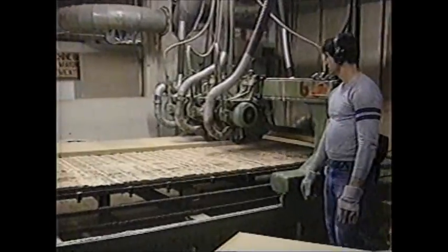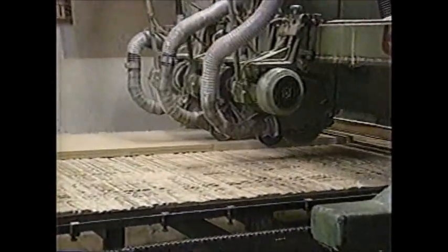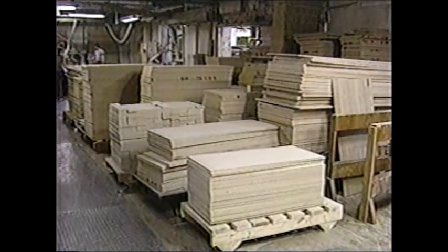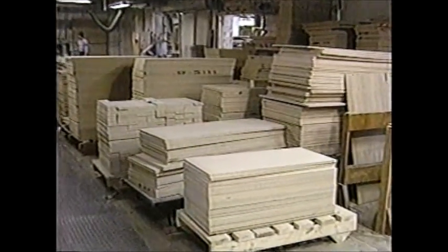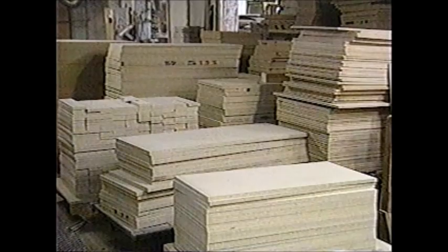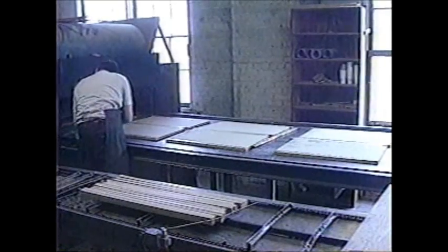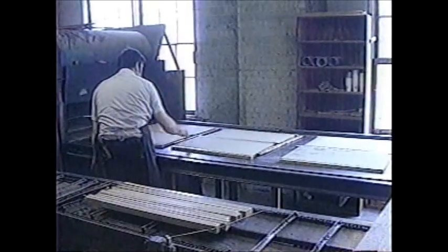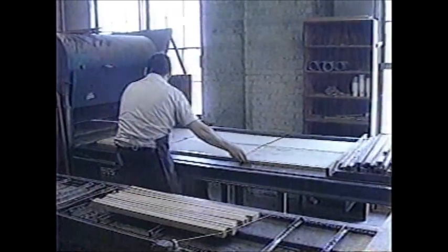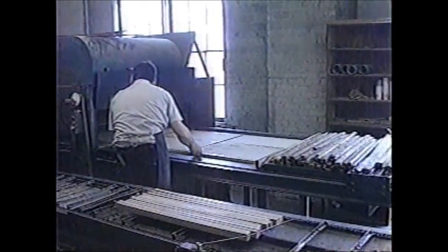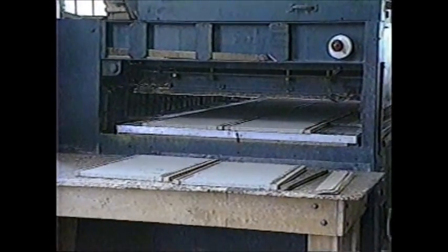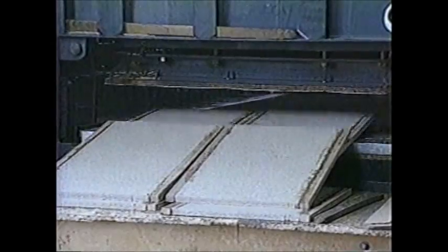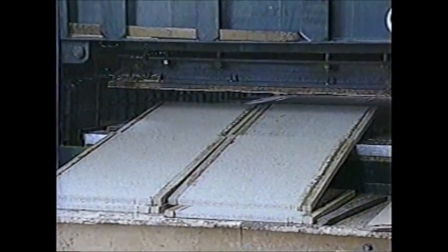Here panels are being cut to size. To minimize waste, required sizes may be special ordered or panel breakdown must be carefully planned. Particle board cores are often edge banded with lumber before the veneer surface is applied. The lumber edge can be machined, will hold screws, and can be finished to match the veneer surface.